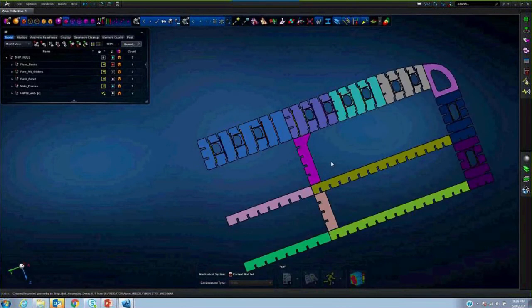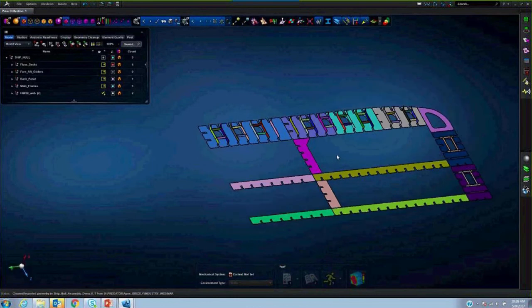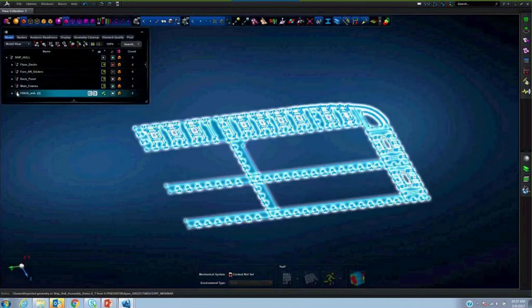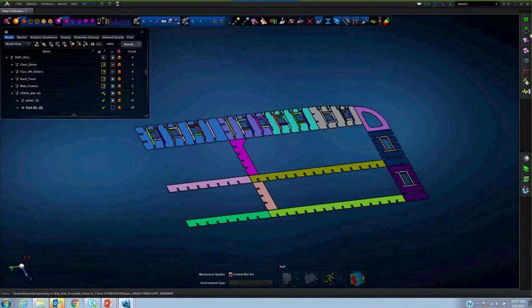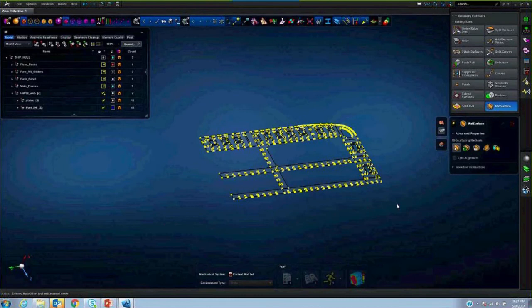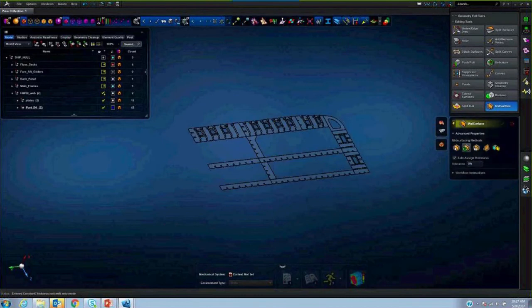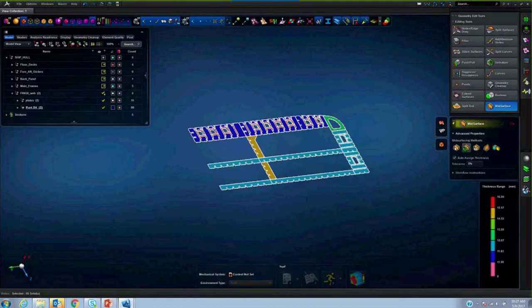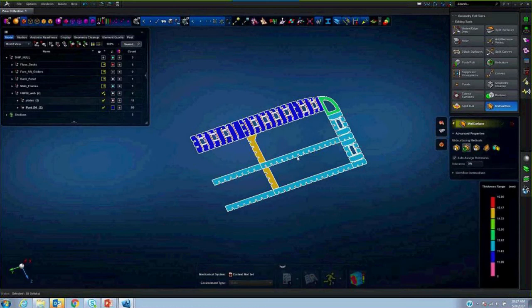And how do we really de-feature those things in Apex? The process in Apex is quite simple. Let's go through first creating mid-surface geometry for all these parts, and let's use the constant thickness approach, and let's create mid-surface for all these parts. Okay, and it created maybe multiple parts and assigning different thicknesses.